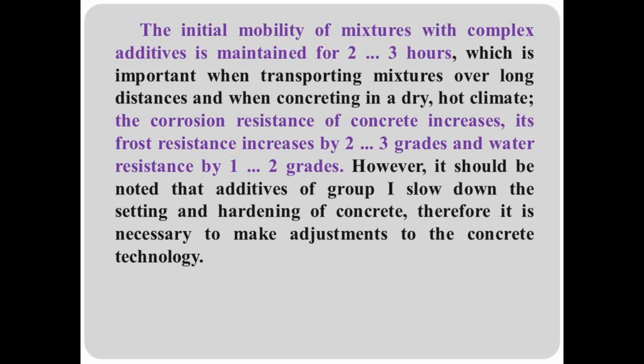The corrosion resistance of concrete increases, its frost resistance increases by 2-3 grades and water resistance by 1-2 grades. However, it should be noted that additives of Group I slow down the setting and hardening of concrete. Therefore, it is necessary to make adjustments to the concrete technology.